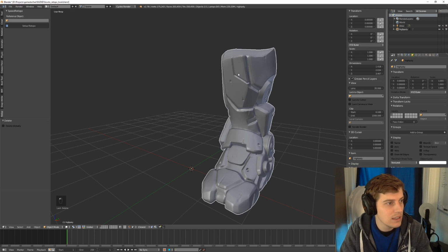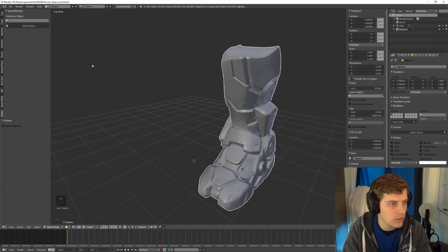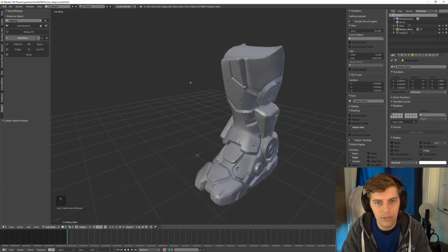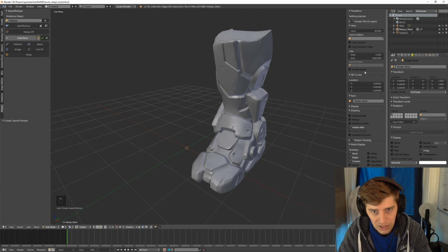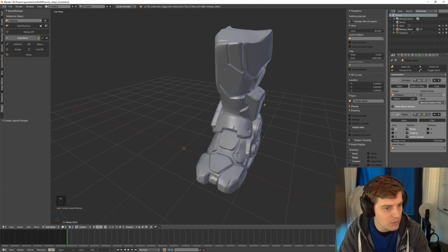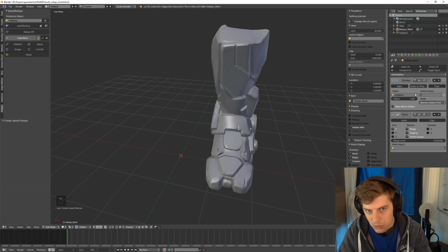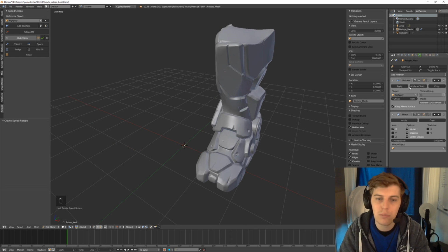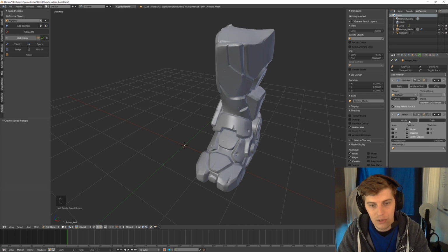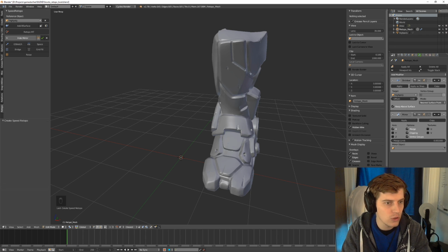So let me start off by showing you how to use this tool briefly. And I'll link you to his introduction video that's more in depth about how to use it. But I just want to give you an idea of the kind of stuff you can do with this tool. So you basically select the high poly here, and then you press Setup Retopo, and then you're in kind of retopo mode. This does a whole bunch of things in the background that you may not notice. One of the things it's done is it's created a new mesh, which is your retopology mesh, and then it's created a bunch of modifiers on this retopology mesh, and specifically shrink wrap and mirror. So it's shrink wrapped your new mesh to the high poly mesh, and it's created a mirror, but since I don't have any geometry yet, you don't see anything, right?